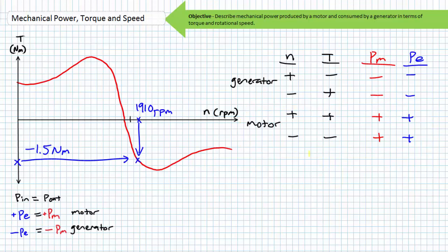You may not find this clockwise, counterclockwise convention universally applied because my royal jurisdiction only extends so far. However, if you can understand the fact that motors exert torque in the same direction as rotation, and generators oppose movement by exerting torque in the direction opposite of rotation, you'll do just fine. Sticking with this polarity convention, though, makes it easier to keep your house clean and figure out who is doing what.